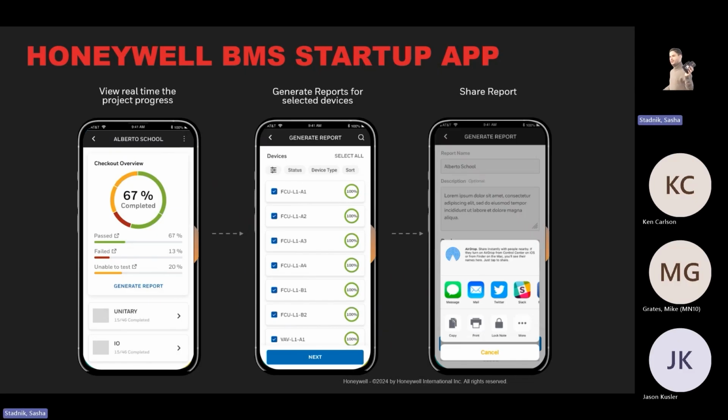Because you will have to do the same for this. So if you have an advanced controller, Bluetooth or Wi-Fi, you can use the same wiring checkout app. And if you have a train of those babies in here, you don't need a license in this one. Just go into your mobile phone and then start configuring this, even if they don't have LED display on. But now you have on your mobile phone a way to push that configuration to the IOs.